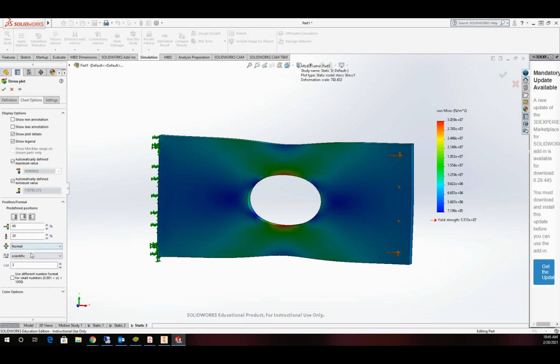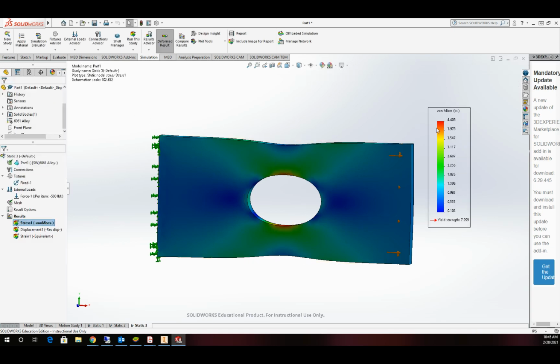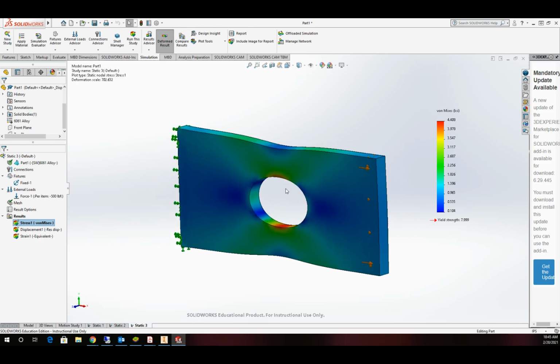My recommendation is we try and use the curvature mesh as often as possible. It's a good starting point. So even though we have tried the other methods, this is probably where I would begin most of my modeling with FEA in Solidworks. So here we're coming in at 4408 as our first value. I would probably refine the mesh one more time using this method and slide that bar over a little bit and see if I can keep the values tight.